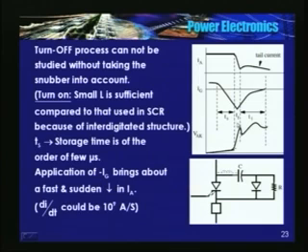So the anode current has fallen to a very low value at the end of the TF period. It is known as the fall time, and this is very small. And from there onwards, what is known as the tail current starts flowing through the snubber circuit.